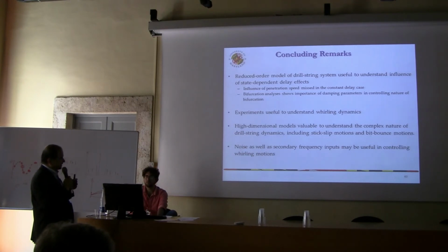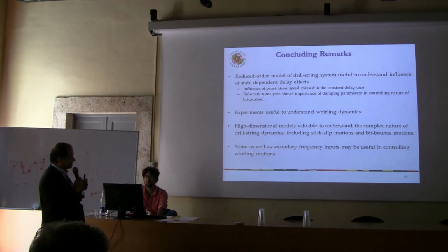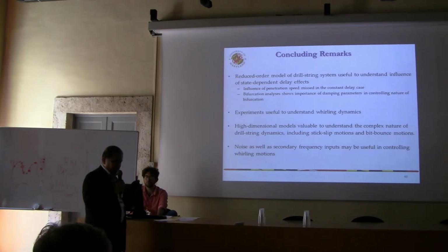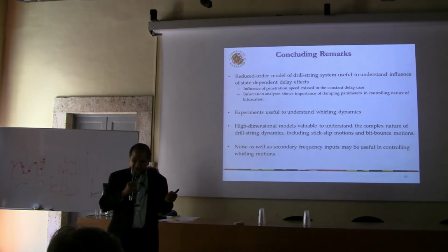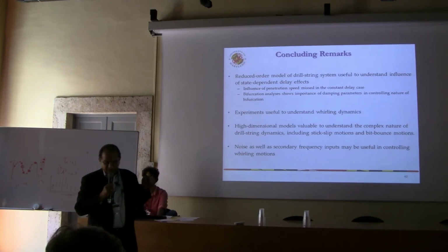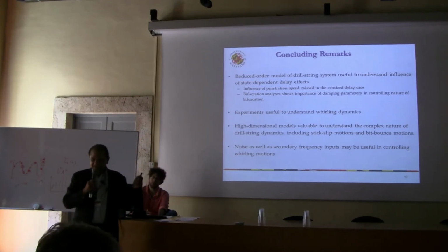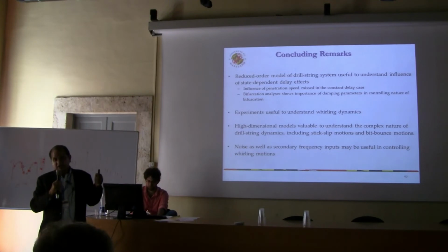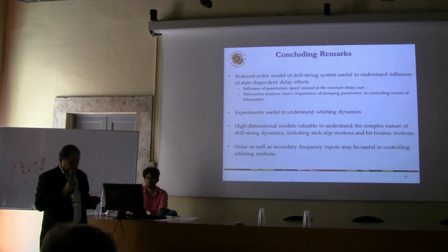The bifurcation analysis shows important damping parameters and the controlling nature of the bifurcation, that is from subcritical to supercritical. Of course, in all of this, in the reduced model, the mechanics is the key. As you saw, how we model the bit-rock interactions is very important, and the friction that you capture there, the loss of contact, all of those are key aspects.